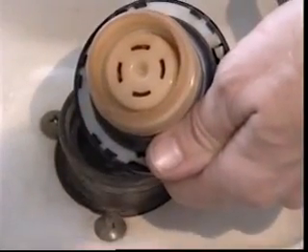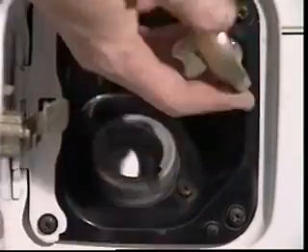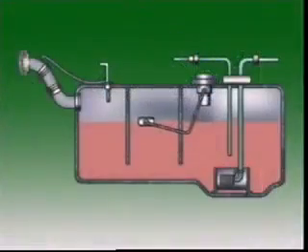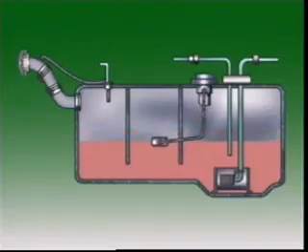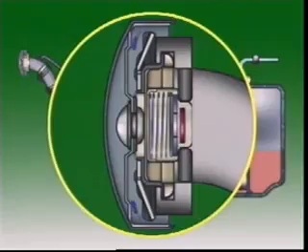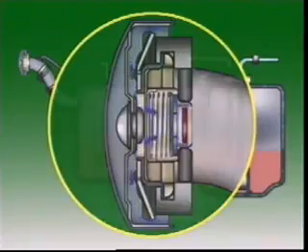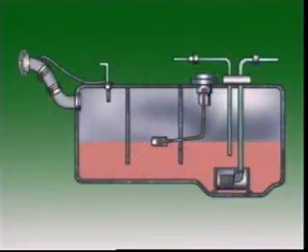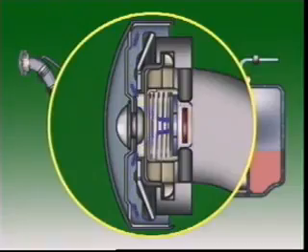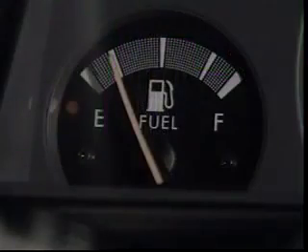Some petrol caps have a low pressure valve built in. It keeps a balance between the pressure in the tank and the outside atmospheric pressure. As petrol in the tank is used, the air space above the fuel increases. This causes a fall in pressure compared to outside atmospheric pressure. The valve then opens and lets more air into the tank. A fall in temperature can cause a fall in the pressure in the tank. The valve opens to admit more air till inside and outside pressures equalize again.